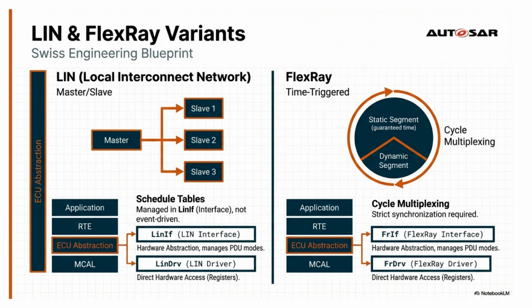Within the stack, the FrIf FlexRay interface module manages the alignment of PDU transmissions with their assigned slots and cycle offsets, while the Fr FlexRay driver handles the register-level interactions with the internal or external FlexRay controller. Together, these protocols allow the AUTOSAR Comstack to scale from simple body electronics to high-performance, safety-critical vehicle control.